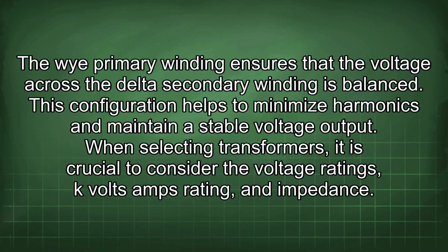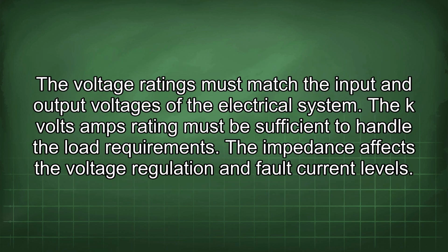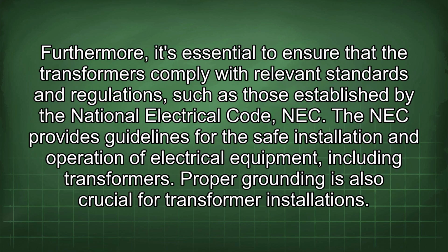When selecting transformers, it is crucial to consider the voltage ratings, kVA rating, and impedance. The voltage ratings must match the input and output voltages of the electrical system. The kVA rating must be sufficient to handle the load requirements. The impedance affects the voltage regulation and fault current levels. Furthermore, it's essential to ensure that the transformers comply with relevant standards and regulations such as those established by the National Electrical Code (NEC). The NEC provides guidelines for the safe installation and operation of electrical equipment, including transformers.